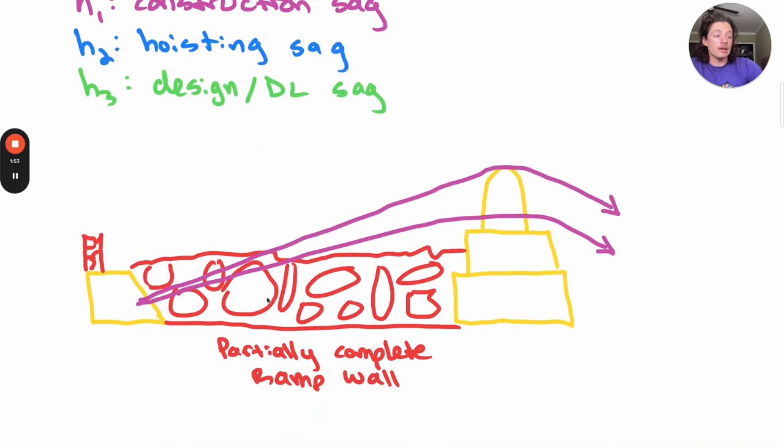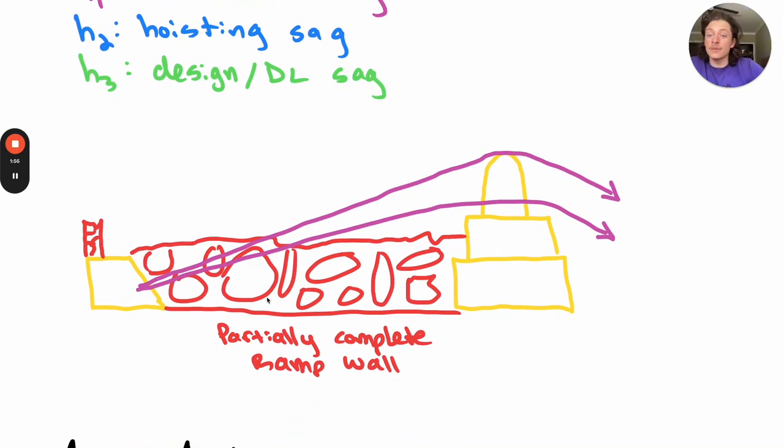Now, although the forces from the self-weight of the cable is not nearly as much as the full dead and full dead plus live load, we do need to consider that a large portion of the abutment fill will not be in place, and the ramp walls will not be completely built, as well as the back wall might not be built. And the concrete has not had that much time to cure. So we can use these conditions to check our design for adequacy at this construction phase.